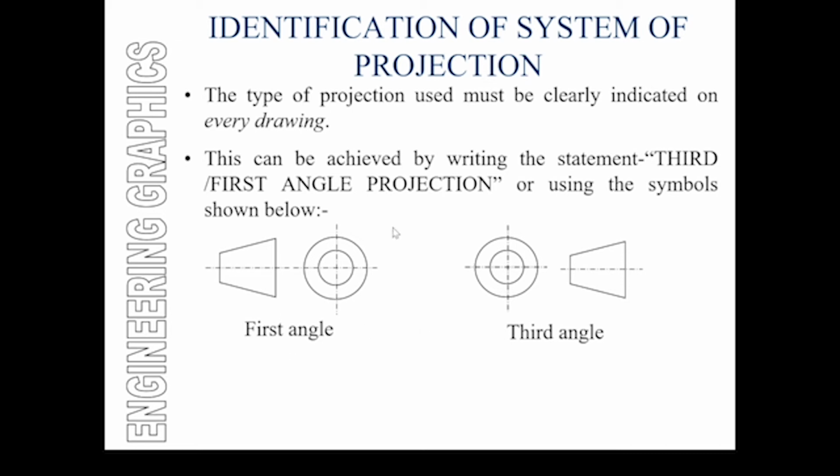I tend not to think about the first angle system, but I know if I'm looking at a cone here, basically a slice of cone, I would see two concentric circles like this if I'm looking at it from the left hand side. So to me, that stands out as a drawing produced in a third angle system, hence I remember that as the icon of that.